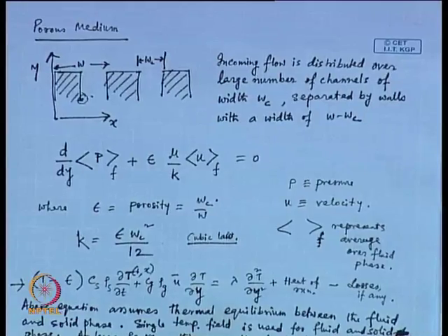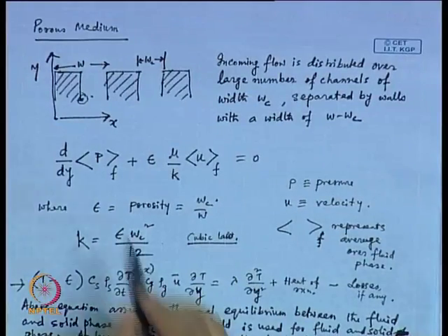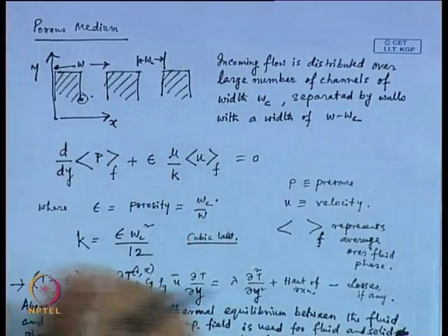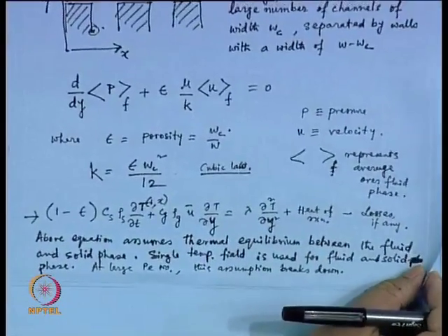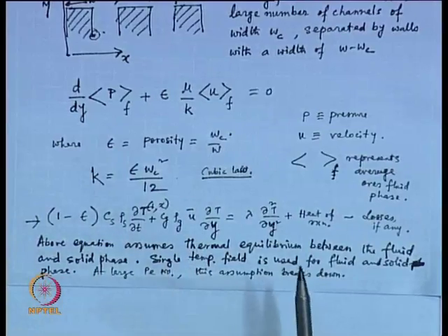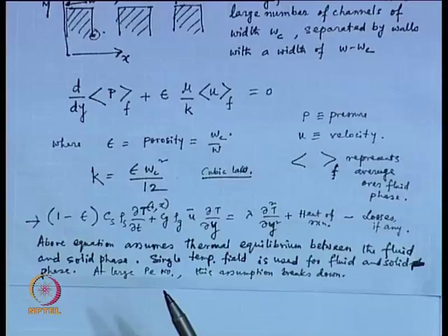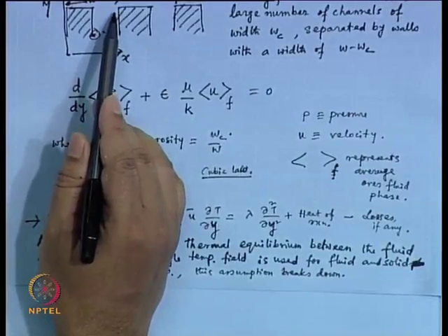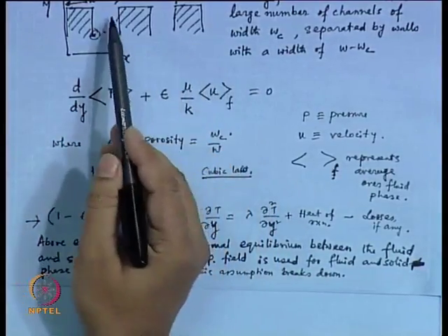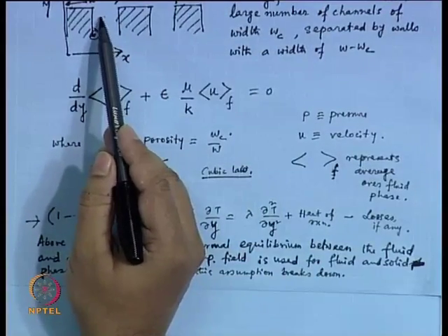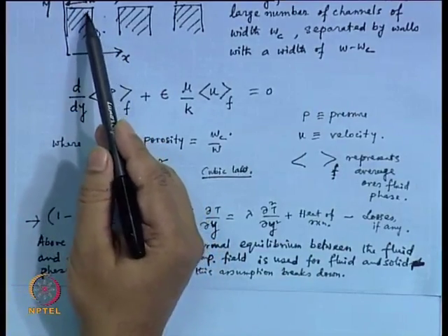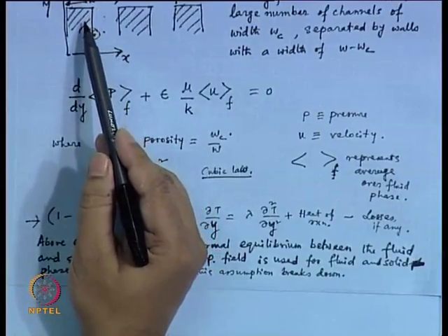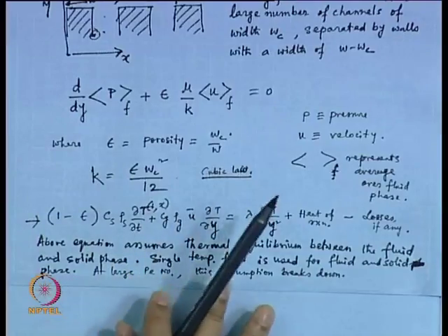That means we are talking about UF, which is averaged over the fluid phase. Within the fluid phase we are not differentiating layer by layer or any profile; we are not adding a velocity profile or anything. Now, you come up with the temperature and the heat balance equation. Ideally, you should have two temperatures, one for the fluid and another for the solid, and the fluid temperature should have a profile within the channel. If it is an exothermic reaction, the temperature would probably be maximum at the center of the channel and lower as you proceed towards the wall, and there should be a continuity of flux at the interface between solid and fluid. There are all kinds of things which need to be considered if you are really looking for a rigorous CFD model.